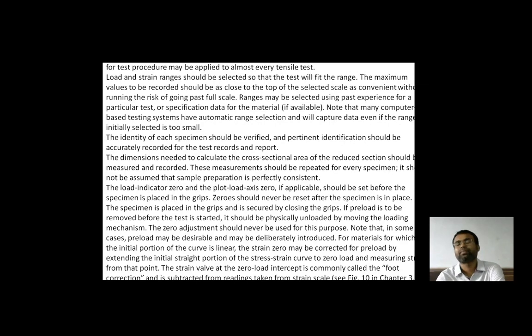Now, after loading the specimen into the test machine, we follow the particular steps for proceeding with the tensile test. And for this test procedure, the same rule is applied as in all of the tests. So load and strain range should be selected so that the test will fit the range. The maximum values to be recorded should be close to the top of the selected scale as convenient, without running the risk of going past full scale. So this needs to be taken care of.